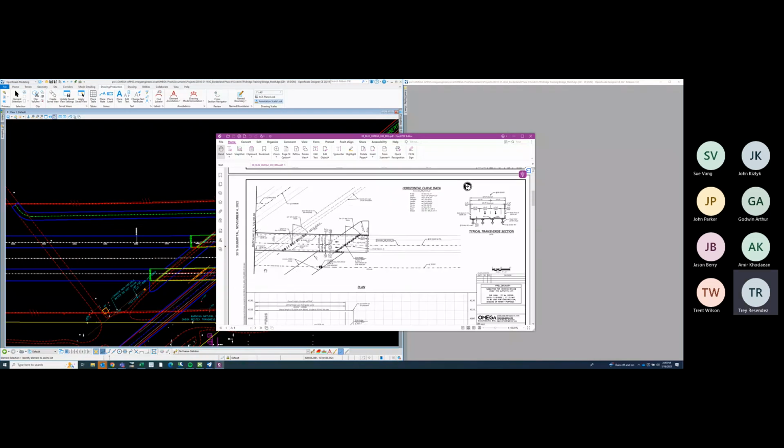So now what you need to do is place your named boundaries, is what they're called here. What named boundaries are, basically, if you can see my PDF here, is the box that is within the sheet, or the box that you want to show inside the sheet. So really, we need to create a named boundary for this plan view here, and then also for the second sheet.